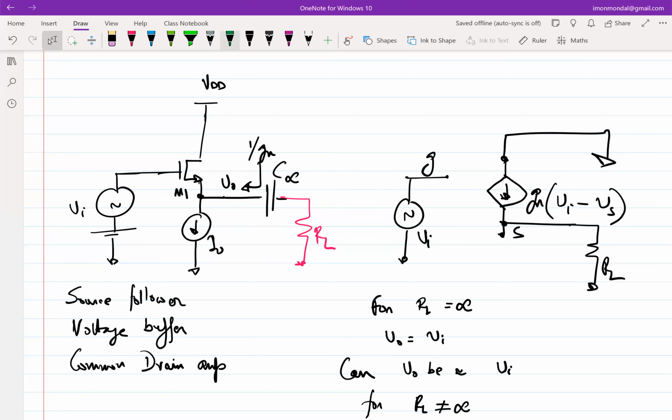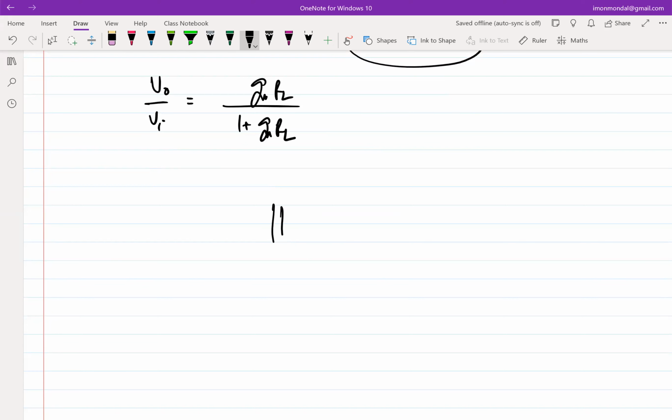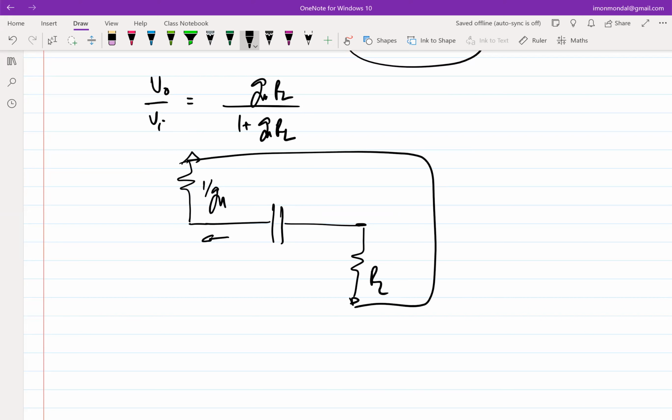So essentially, if I sit on the capacitor, if the capacitor is a black box, this side the resistance is 1 over GM, right? This we figured, incrementally grounded. On the other side, I have RL. So this is the loop. So the capacitor C sees an equivalent Thevenin impedance of 1 over GM plus RL. So C infinity has to be much greater than 1 over omega naught times (RL plus 1 over GM) for it to behave like a short circuit.